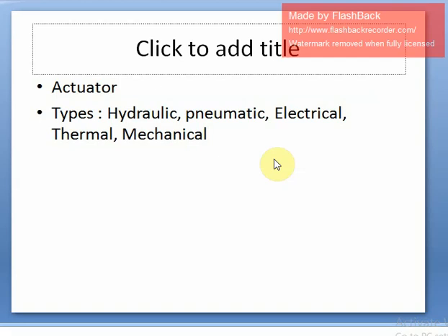A hydraulic actuator consists of a cylinder or fluid motor that uses hydraulic power to facilitate the mechanical operations, right? When some fluid passes through, the motion is converted into linear motion, accelerating motion or rotatory motion, and since liquids are nearly impossible to compress, most hydraulic actuators basically exert considerable force, right?